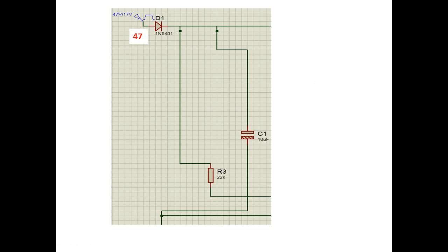After, we will have 46.3, which means the difference between the voltage of cathode and anode is supposed to be 0.7. As I said, the capacitor keeps a level of voltage for a period of time. So that means the 46.3 volts must stay constant for a period of time.